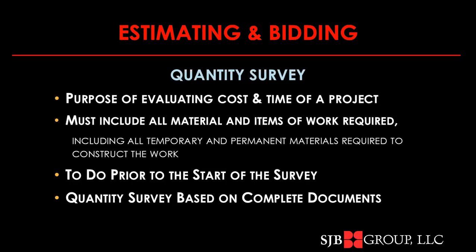The quantity survey needs to be based on complete documents. You want to use one set of bid documents for a control set as you're doing your estimate. And you'll want to develop a coding system so you'll know what part of the project's work has been taken off, the quantities that have been pulled off in support of the estimate. You'll want to check that all addenda are included in this control set. And you'll want to review the bid form for the specific breakdown of the prices, the way you're going to have to do your takeoff to pull together your bid pricing.